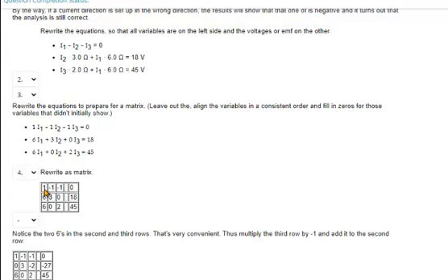So as I do that, I'm just going to write down the coefficients. That's what I meant to say, coefficients, not factors earlier. And so you see the 1, -1, -1. Those are the currents with the junction rule, and then here are the voltages. So that's the loop rule for the upper one. It's the loop rule for the second one. And now I need to analyze that matrix, and I'm going to do that on a calculator.